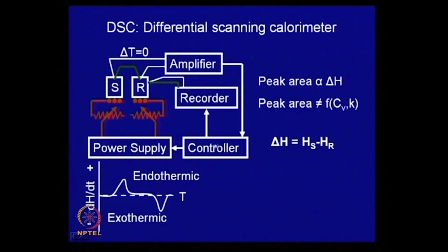And what the controller does, the controller tries to control this temperature difference, it will try to keep it 0. So, that means it has to supply a differential power supply, a different amount of power will be supplied to the reference material and the sample. And in fact, what you are going to measure is the amount of power, or heat, that you supply to the sample, and the power that is supplied to the reference material, and